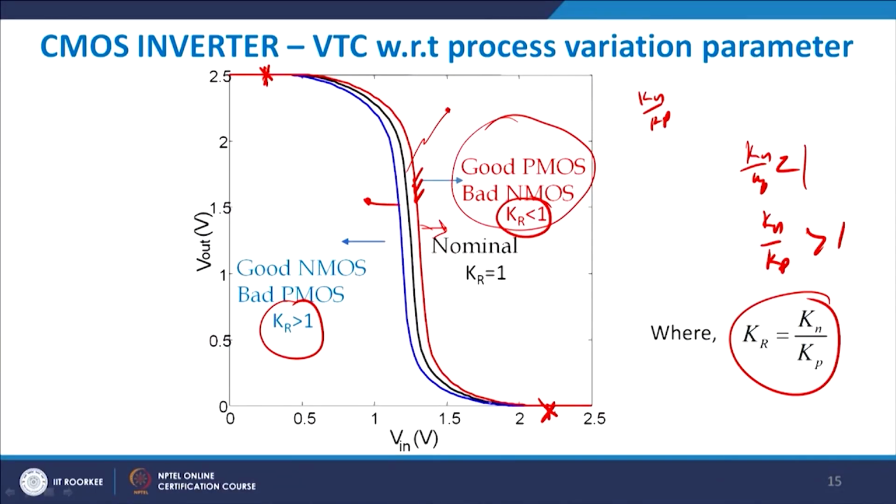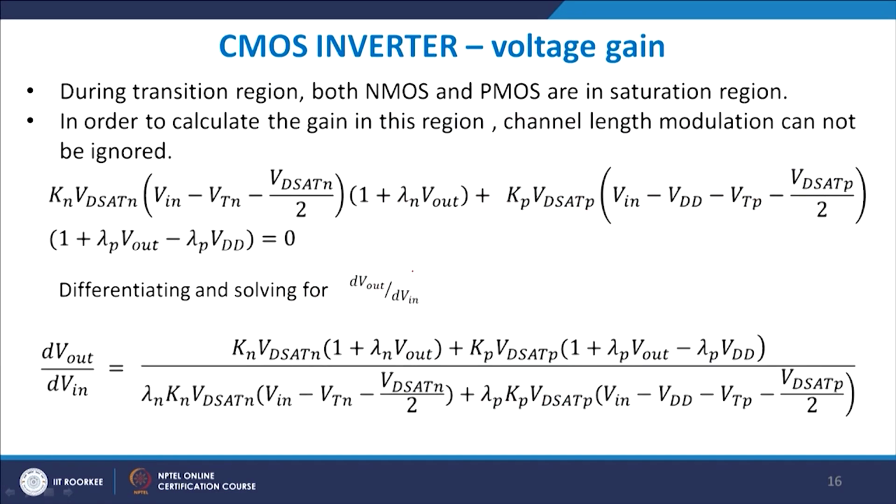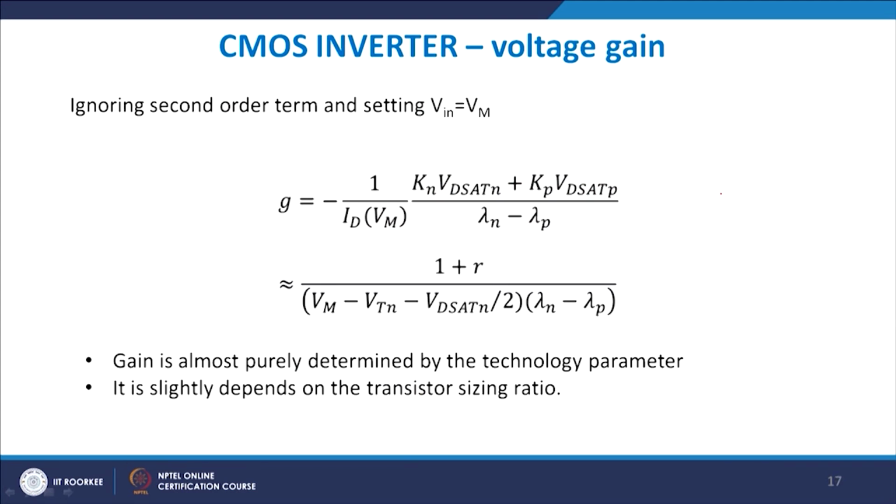From this graph, you can see that I can switch from this point to this point and go from logic 1 to logic 0. This is output logic 0 and this is output logic 1. Somewhere in the middle, the gain here will be 0 and the gain here will also be 0, but in the middle your gain will be a strong function of your Vin, because if you remember, Av equals dVout by dVin. Writing down dVout by dVin, you get this big expression which is important.